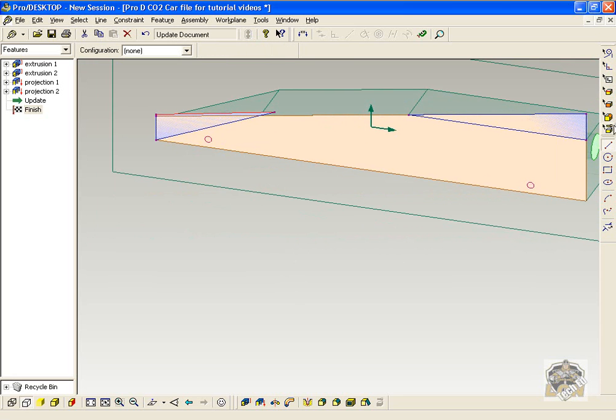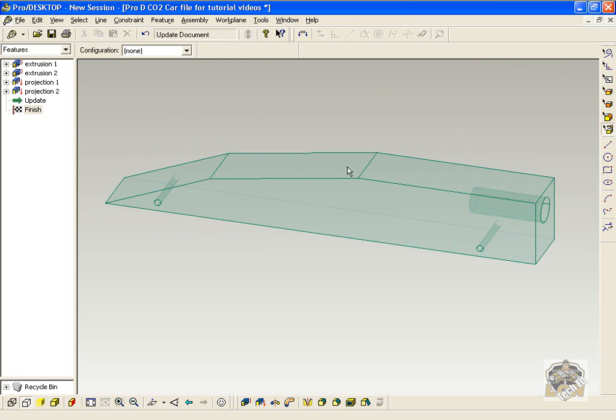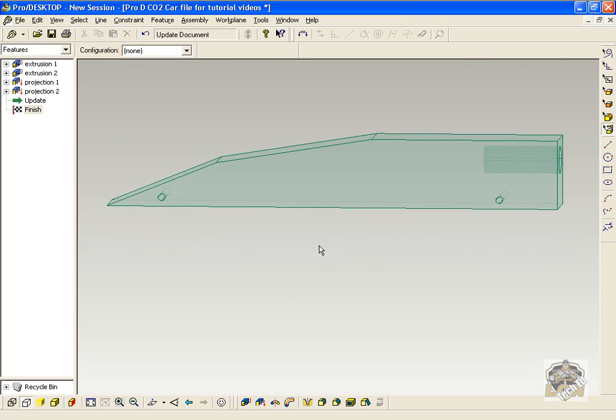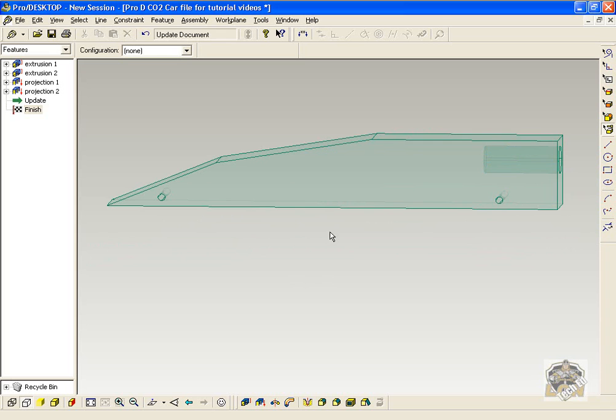And what I'll do is I'll click over here on 3D view, take the sketches down, and now I have a more aerodynamic body. Still, if you ask me, it doesn't look the sleekest. We'll adjust it. But I don't want to create something that looks totally cool. I want you guys to handle that. It's your car, and use some of the tools to do that.